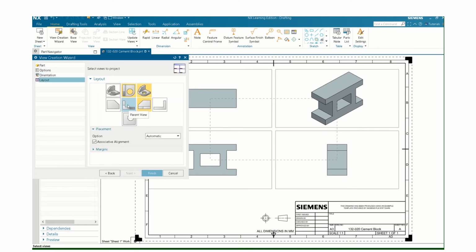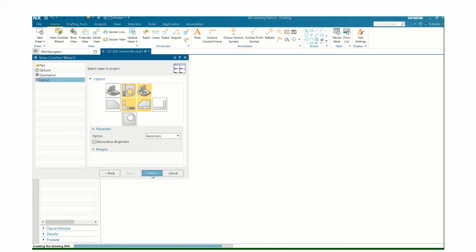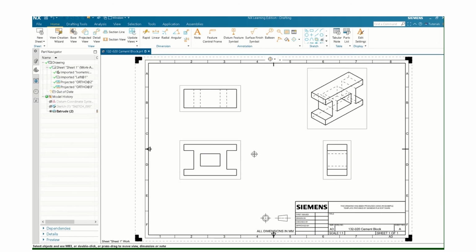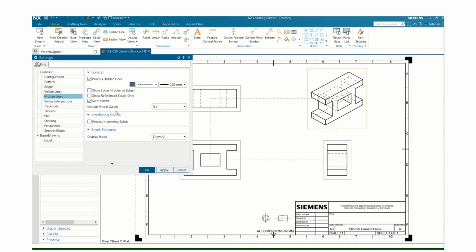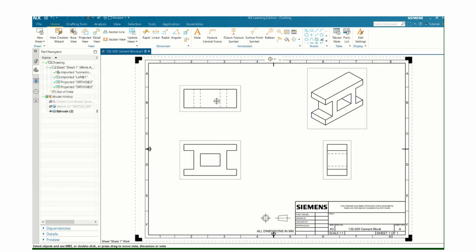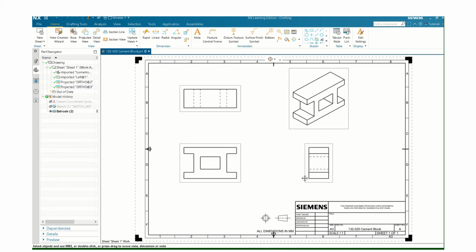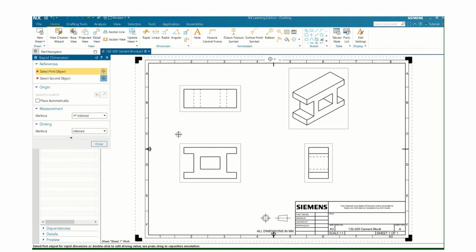So what I was doing is kind of defaulting to my previous drawing. So that's kind of a typical way we're going to draw. And let's finish that. We should see our hidden lines. We'll turn those off. So double click on there, turn off the thing that says self-hidden, say okay. And we are good to go with our model. We will want to dimension that. Clicking on endpoints, and again, we're stuck with ISO dimensions, which is just what it is.